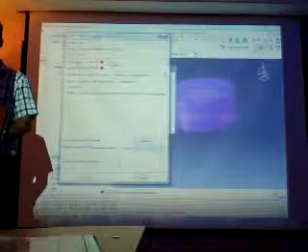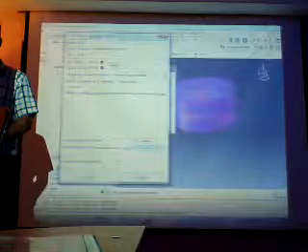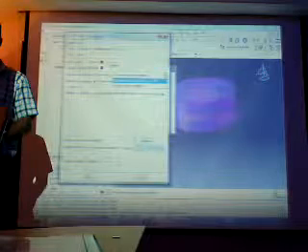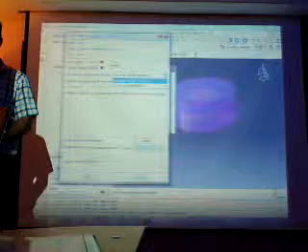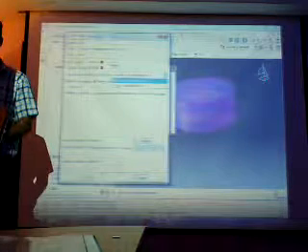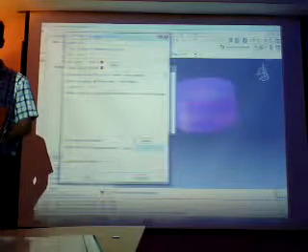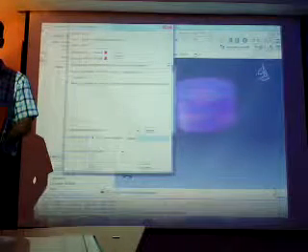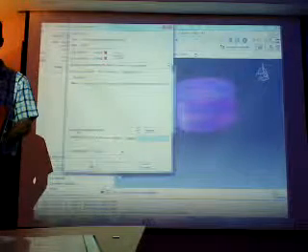You see here, first surface picked already, second surface picked already. Here you have two different kinds of mechanical constraint formulation, kinematic and penalty. Kinematic is more accurate than penalty, but the computational time for kinematic is too high. Penalty is okay for our simulation. For sliding formulation, you can refer to the documentation to see which of them is okay. Finite sliding for metal forming, always advised by Abaqus.